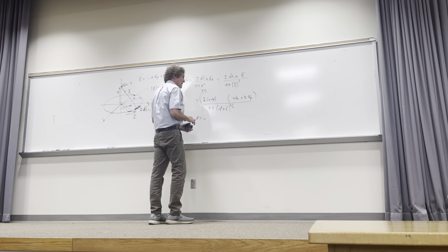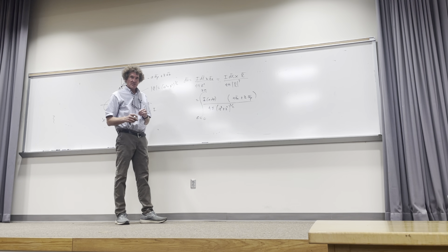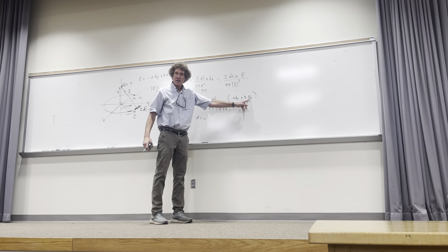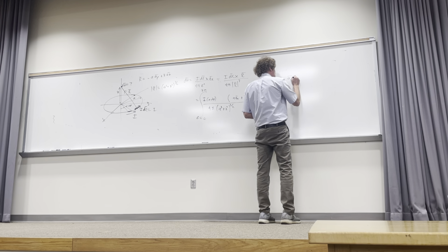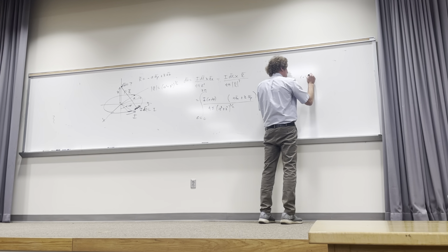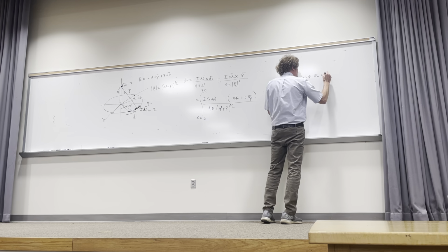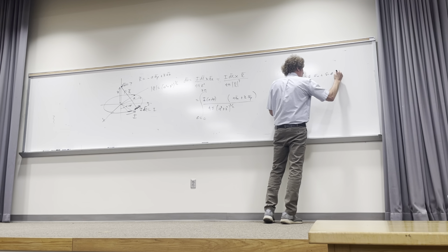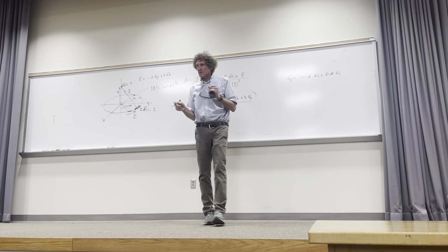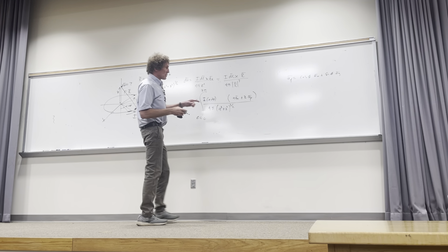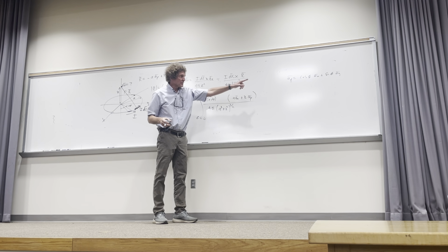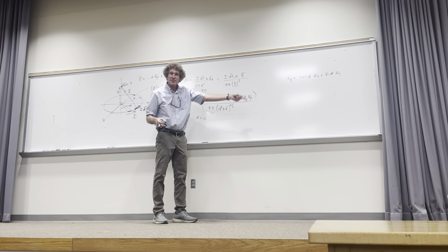You're right. But I have a statement here. You see how it has a rho here? Now, technically, I'm not going to spend a lot of time on this. a rho is actually equal to cosine of phi a_x plus sine of phi a_y. Promise you it is. And if I replace a rho here with that, just listen to me. What happens when I integrate cosine of phi or sine phi from 0 to 2 pi?